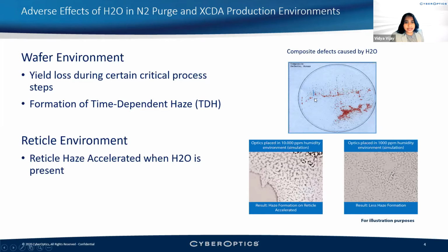Here you can see when there is some humidity or water vapor present in the wafer, if we further use this wafer to make ICs, there are going to be many failures. Also, when the wafers are stored in polymer cases, it can have a haze effect, which is, as you keep storing the wafers in the clear case, you can have some light scatter, which increases over time.